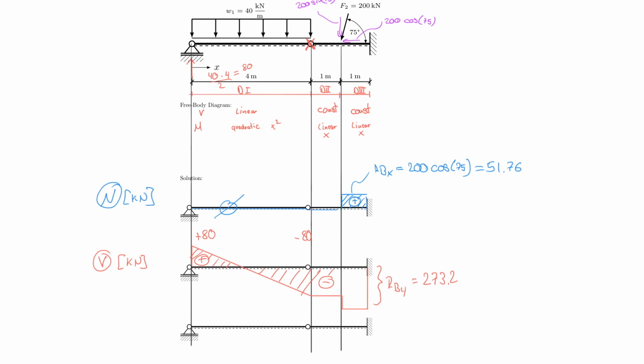And it's important to note, for somebody who has never dealt with these hinges before in the diagrams, that there is a shear force value here at the hinge. It's a very common mistake that students start to believe everything there must be equal to 0, but that's not true. Only the moment goes through 0. And in fact, let's get started on that.